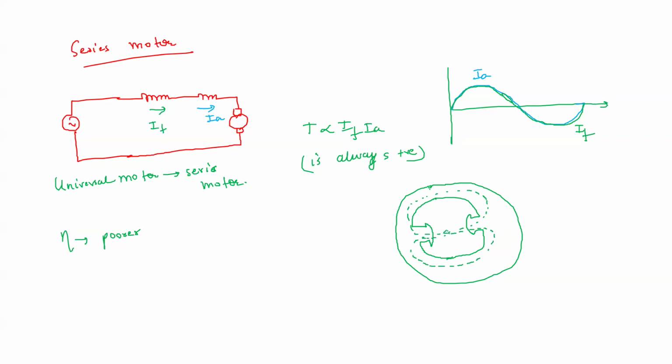But now the flux which is being generated is AC. Before, it was a DC flux, meaning a constant flux, flux DC. But now since we have given it an AC supply, the flux flowing in the stator is phi AC. Previously in the stator, the core losses, hysteresis and eddy current losses, were less in the case of DC.